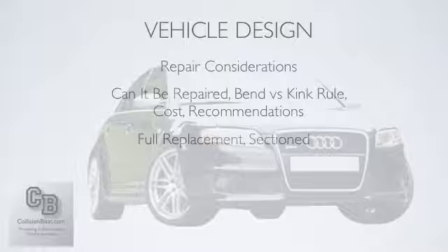There's also the bend versus kink rule. If it's bent a little bit, you can repair it. And if it's kinked, if it's got a real sharp bend, and may even have cracks and tears in it, that's when you're going to want to go ahead and replace. But still, that rule falls under the first one. If it can't be replaced, of course, it's going to have to be repaired.